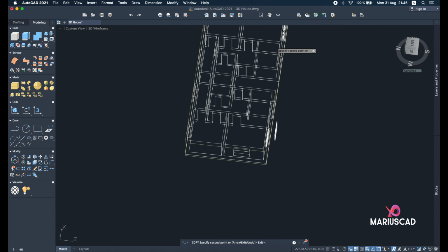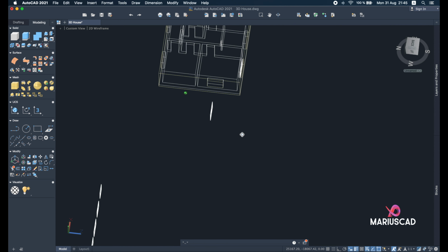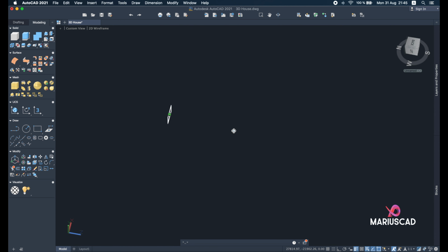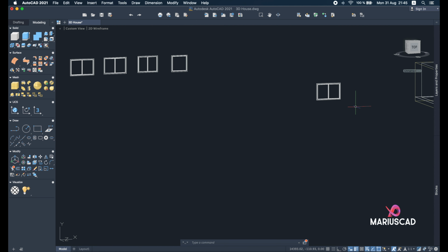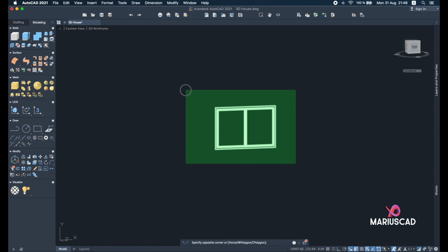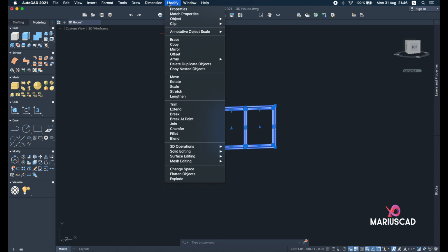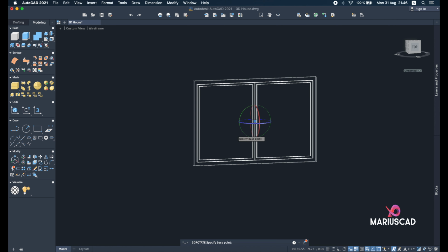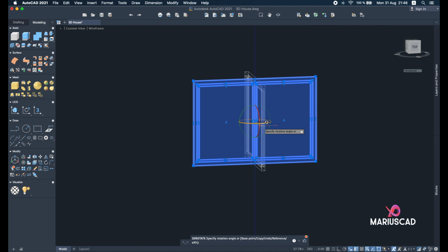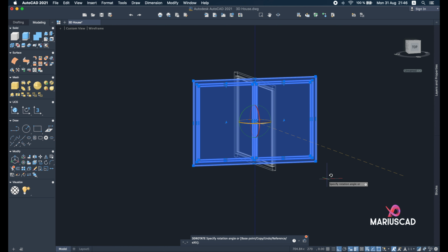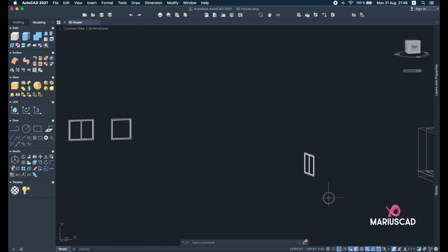And put it a little bit here, because we need to switch it. We need to rotate it. Select this drawing. Yes, and now bring it back, because it's far away from our drawing. Okay, now rotate it. So select it, go with modify, 3D operation, 3D rotate. So I will choose this axis. Don't forget to have the auto command active, otherwise it will not work.